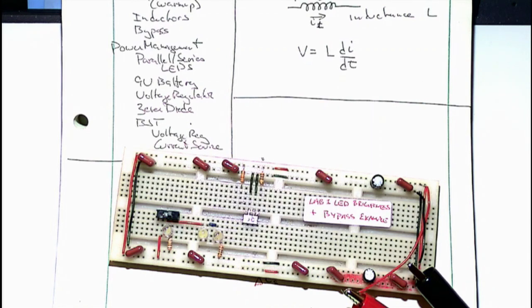And you know, when I start a project, the first thing I do is lay out my power buses, put in some bypass caps, and then I don't have to worry about it. The worst thing is don't put any bypass caps, and then your circuit doesn't work, and then you put in bypass caps, maybe it fixes it, maybe it doesn't. So always put in bypass caps from now on.